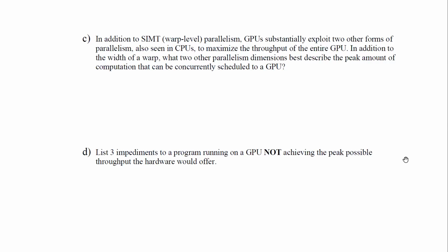And so that's why they don't even bother usually with branch prediction. They have a fairly shallow pipeline. They have 32, 48, 64 warps waiting to be scheduled. They're sitting there, so every lane logically has a thread ready to be scheduled. And so they're very latency tolerant. It's about throughput: lots and lots of threads, and lots and lots of cores. And each of these threads is part of a little parallel warp.